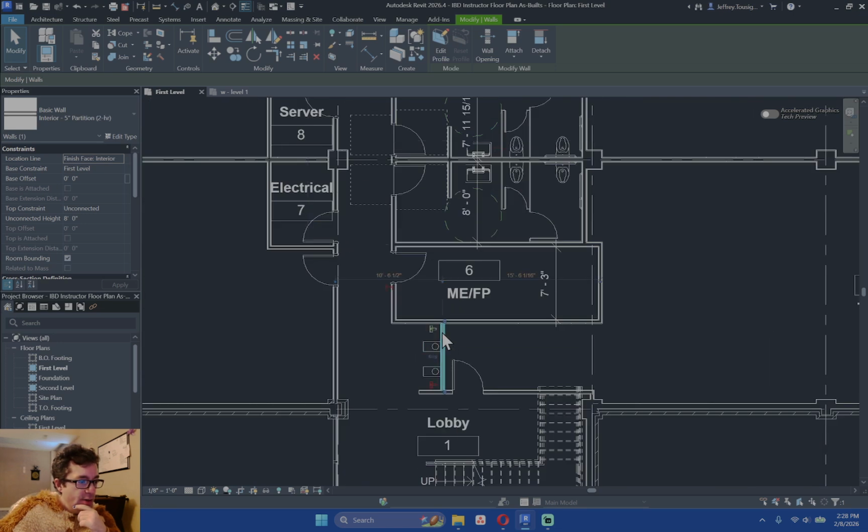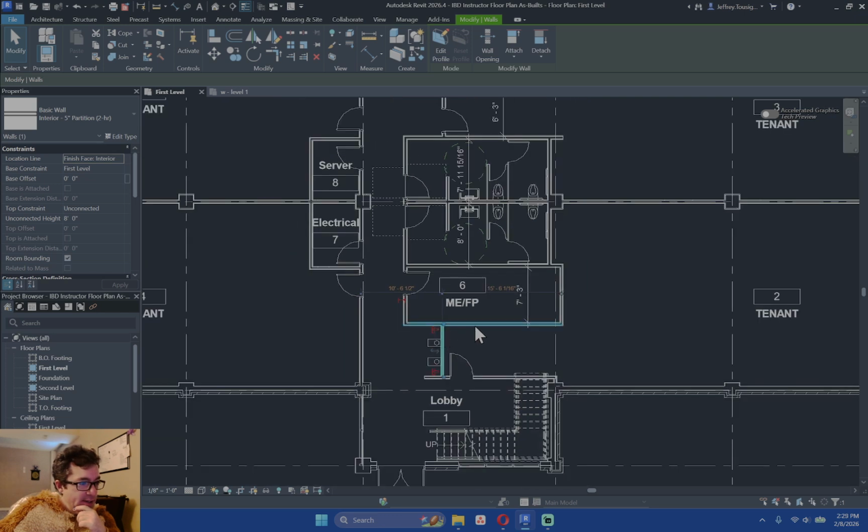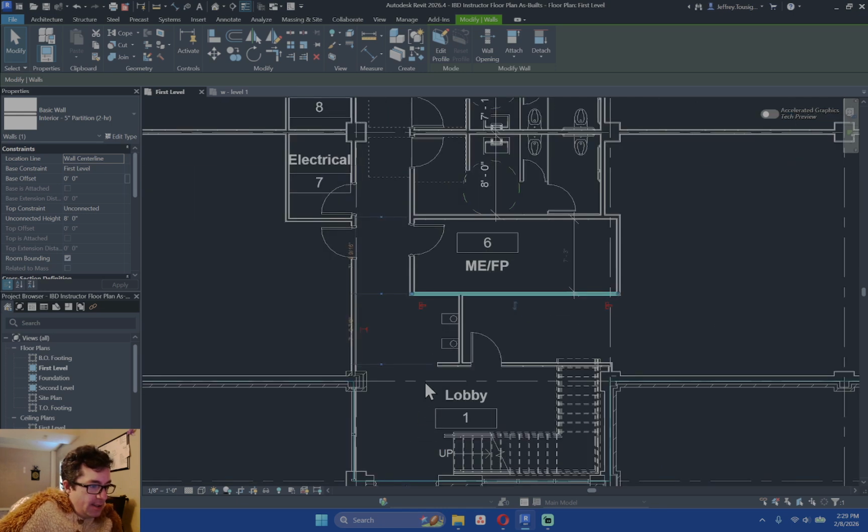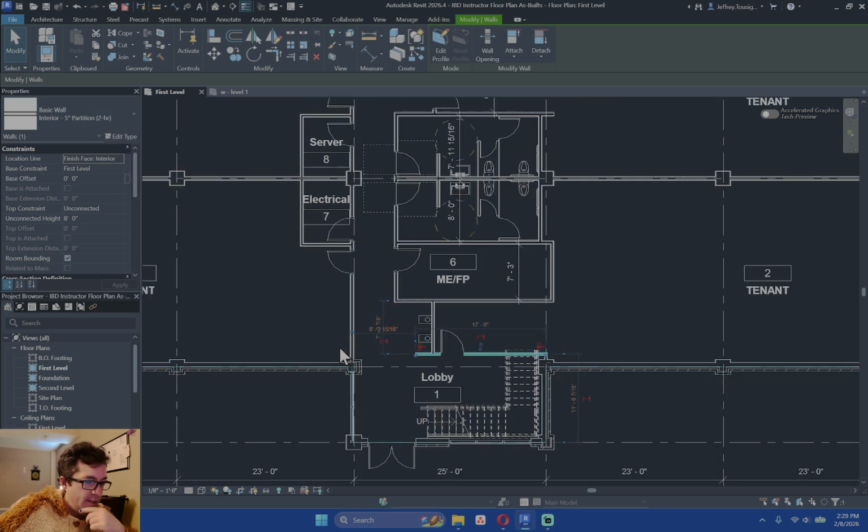This is a design choice based on the tenants that were there. I believe the mechanical and fire room are still being a little bit designed as well. So I could just throw in proposed walls, but for the interest of time, I think I'm just going to get stair walls in. So this is a fireproofed hallway, or it better be, because there is no way to fully enclose this staircase. If we choose to in the future, we can, but we have some more 5-inch 2-hour partitions.